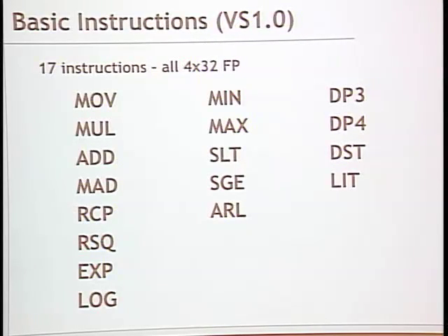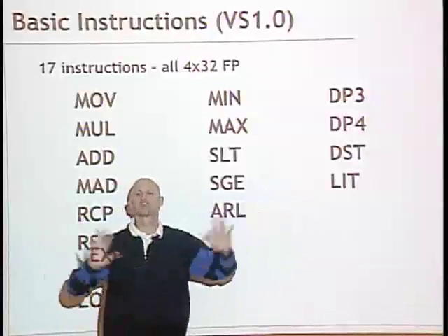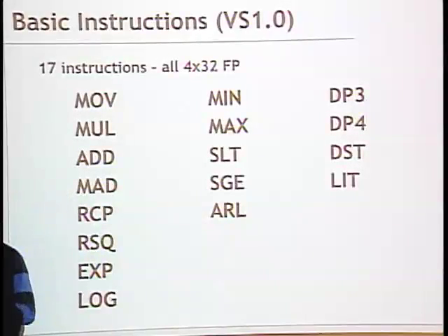So it is the most special purpose instruction you've ever heard of. You hear about CISC and RISC kind of processors and CISC being kind of special purpose. This is like CISC to the nth power. It's crazy CISC. Okay, it only does this graphics thing, and it's specifically because they needed this thing to run just as fast as doing it in fixed function.